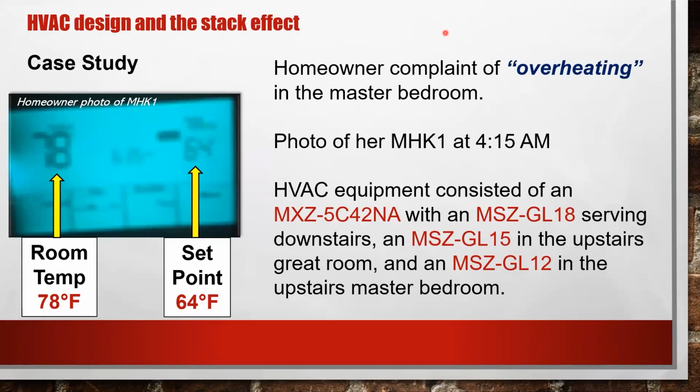This was a photo, rather blurry, I'm sorry, of her thermostat, an MHK1 wireless Mitsubishi stat at 4:15 a.m., showing a room temp of 78 degrees with a set point of 64 degrees. Now, this alone would make me think, geez, it's really overheating.